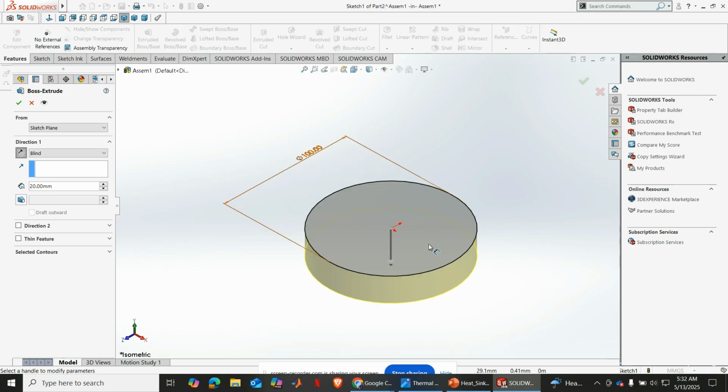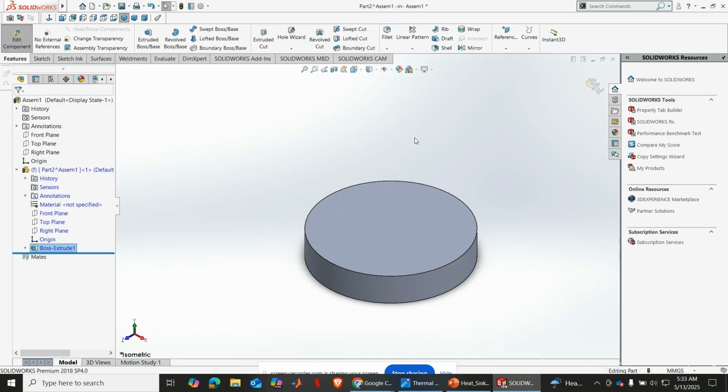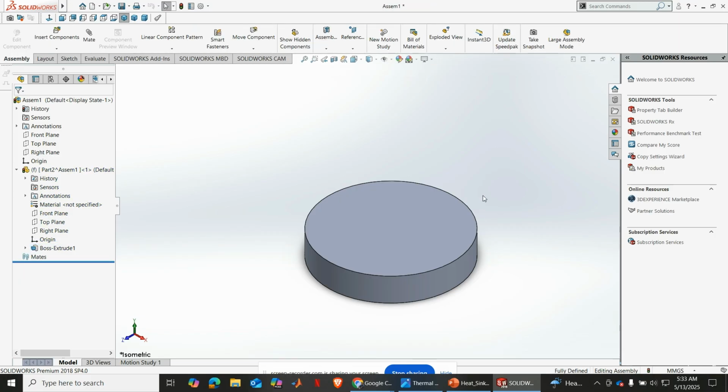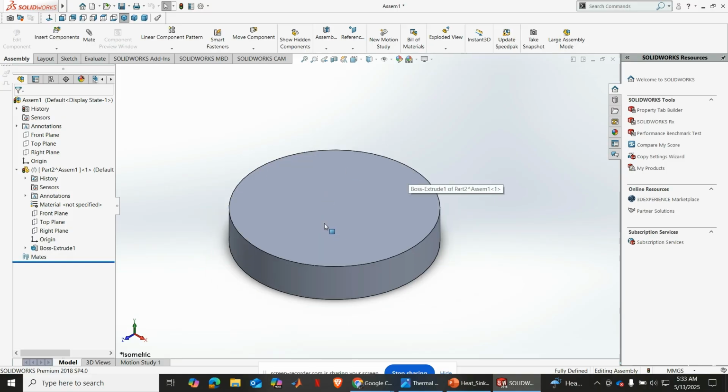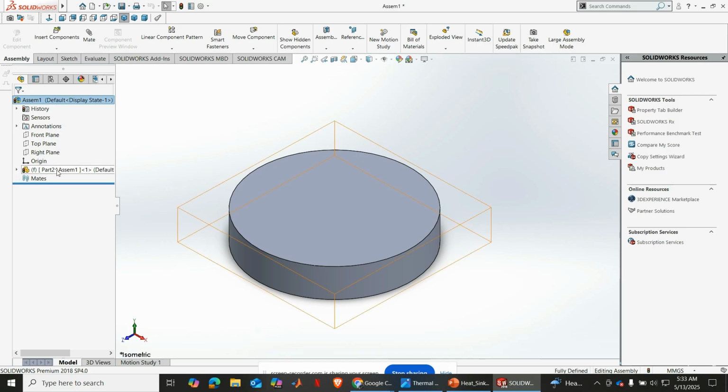Flip direction means you see, we will draw the plain carbon steel part on top of this copper feature. So check, and then here I say save part, right? So here we have our lower copper part. That is part 1, and here it has been given part 2 just as a name.